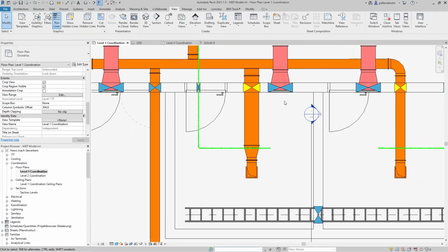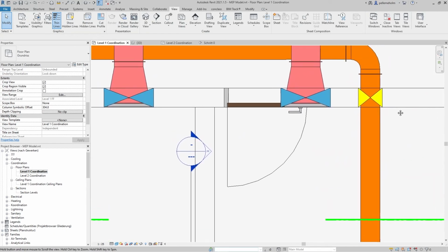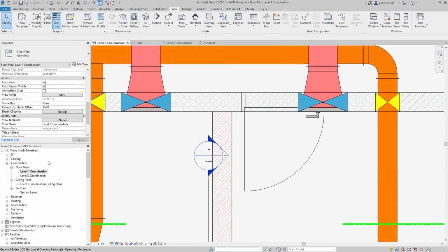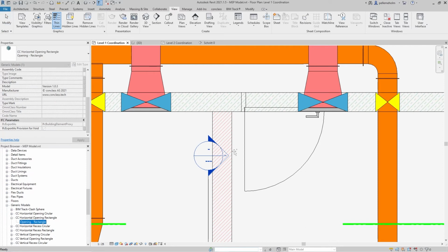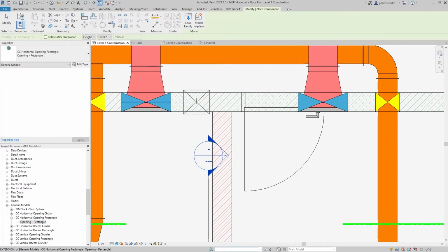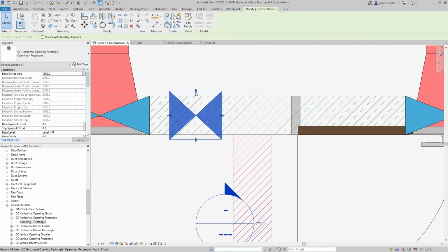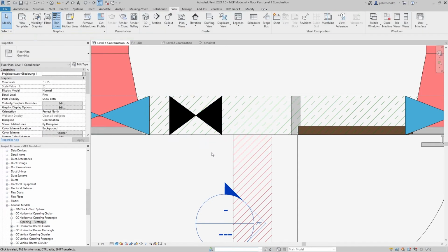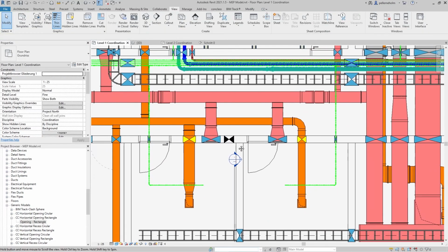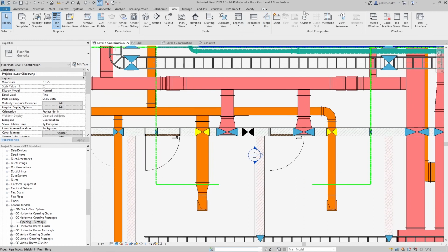You can still place your own openings at any time. This is often the case when there is no MEP element modeled yet. Simply select the conVoid family and place and adjust it as you need it. If an MEP element with similar dimensions passes through the opening later on, conVoid automatically connects them. I will show you that in an example. Just let me create a new section view and the duct.